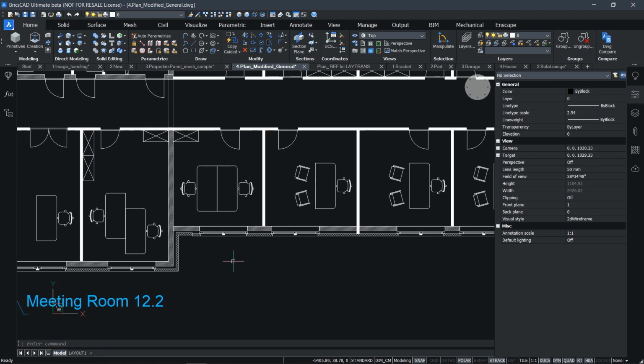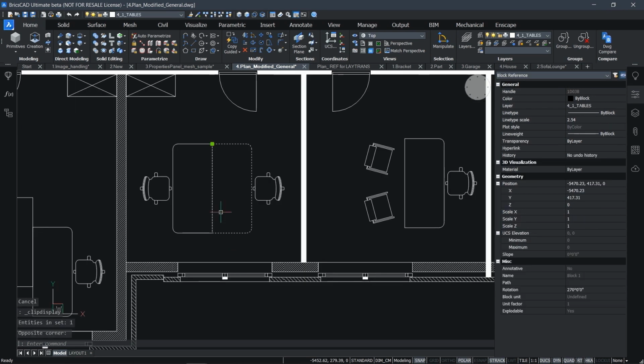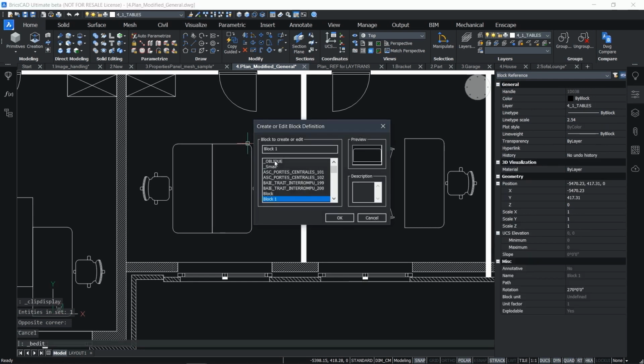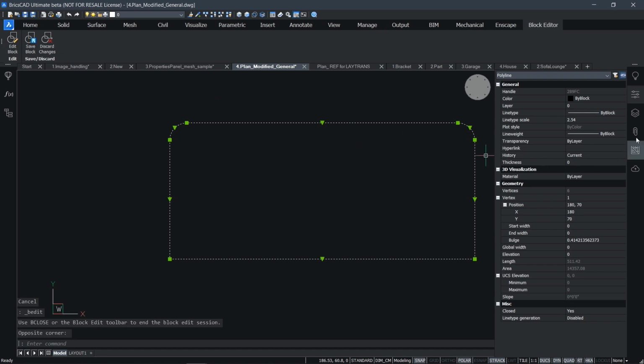I'll continue now with an overview of commands that we adjusted. Either we introduced new commands, or we added functionality to existing commands. You see this 2D drawing. We want to change the color, but for some reason, the color doesn't change. But then we realize it's set by block.